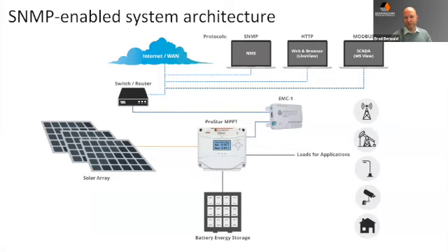And then from that, you don't have to choose just one tool. You can actually use multiple that overlap. So in this case, when I talked about having Modbus or connecting to the site with our utility software MS View, because you need to make some changes to the site, you can do that. At the same time, you can view the HTTP web page to get a dashboard view simultaneously. All at the same time, you can also be using a centralized server to be collecting data from all the sites en masse. And that's done with a network management system or other type of cloud server.